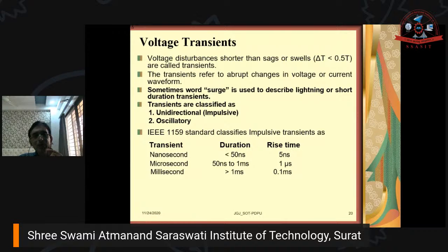Now, you might have heard about unidirectional transient overvoltage. So, lightning is nothing but a unidirectional transient overvoltage. As per the IS standard, we can define the impulse voltage as a unidirectional transient overvoltage which, without appreciable oscillations, rises rapidly to the maximum value and falls more or less rapidly to zero, and is called impulse voltage as per the Indian standard. So the impulse voltages are unidirectional transient overvoltages, and switching surges or switching overvoltages are always oscillatory in nature, right?